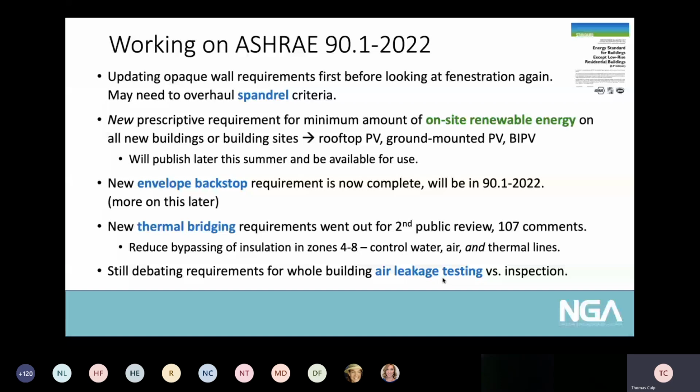On the commercial side, you're going to see a continued triple silver low E market, but increased use of these newer triple silvers that have a lower solar heat gain. There's several companies that provide those. I'm specifically not using their names, but there's at least 3, if not 4 or 5 that offer those, or a low E on tent.